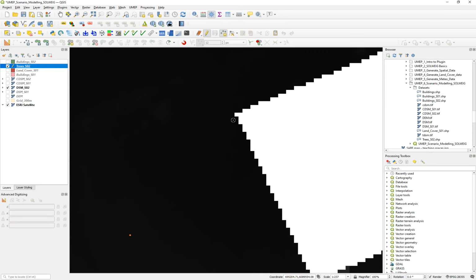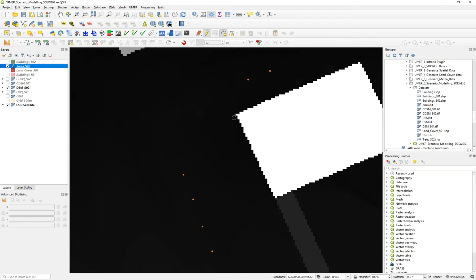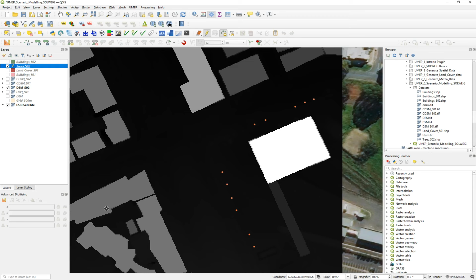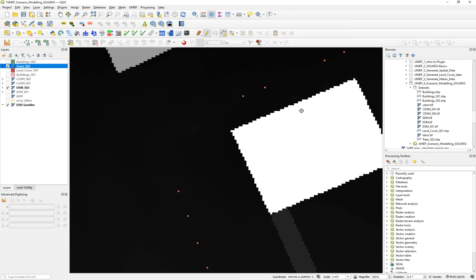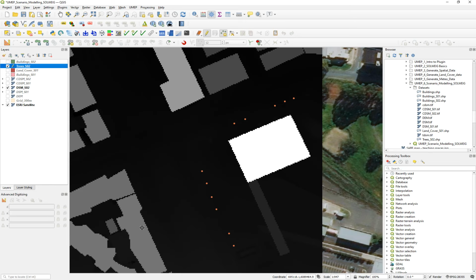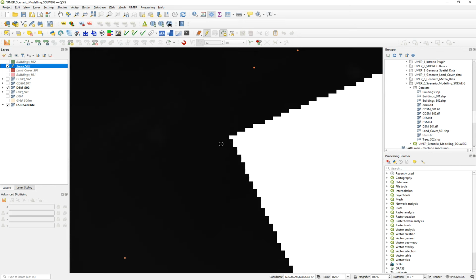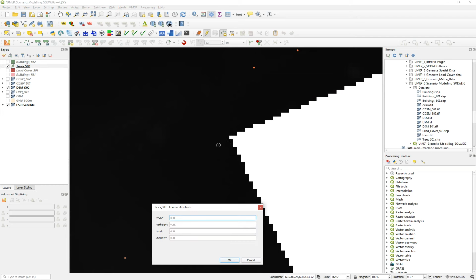Okay, and not too close, because otherwise you will have some issues when generating the canopy, because it considers the location of the buildings. They will be overridden, and then it will be a building in fact rather than a green wall. So let's keep some distance from the wall, and then let's put our tree type as an evergreen.